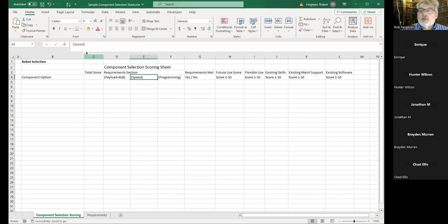Second is speed. We know we have to move that robot between point A and point B at, we'll call it, 3 inches per second. And how do you determine that speed? You become the robot and ask, how fast do I need to move my arm between point A and point B to hit my criteria for cycle times? You have your buddy time you, and you measure the distance, and that's your inches per second.